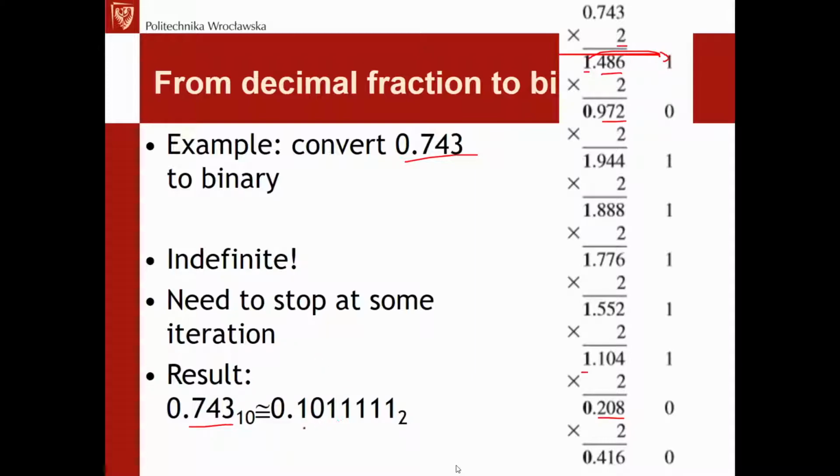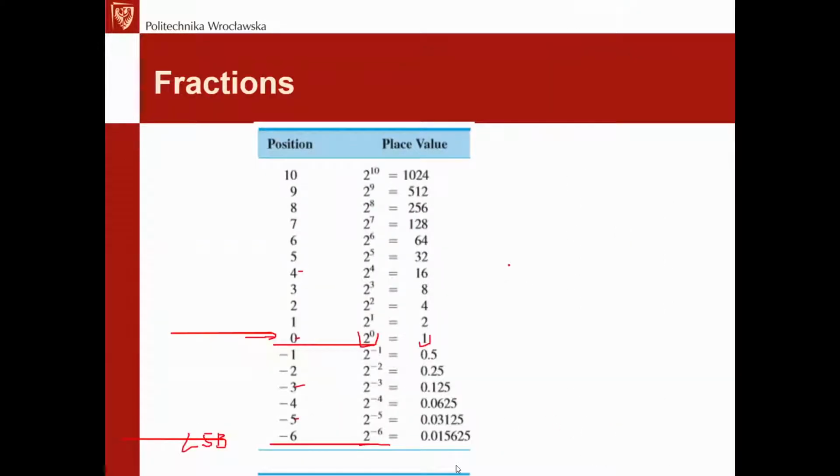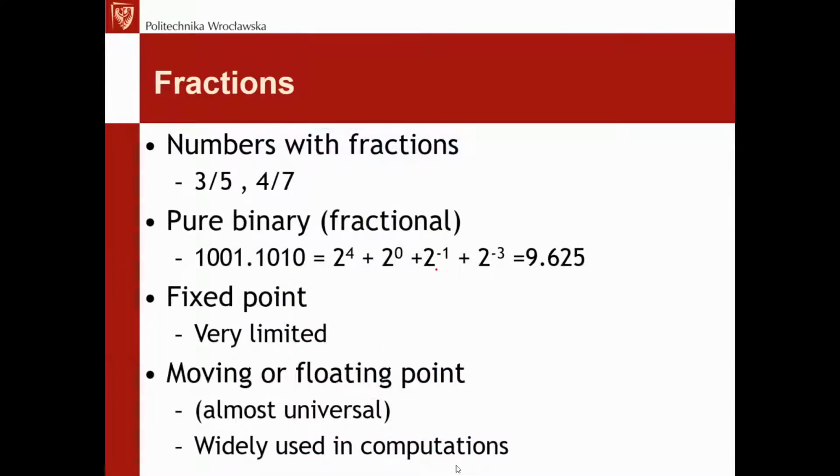Of course, we stop the iteration at the size of our number, the size that we want to use. Going back to practice, there is little sense of using fractionals when we are dealing with 8-bit arithmetics. So in 8-bit microcontrollers, the 8-bit fractionals allow us, like here, a precision of 1/16, which means that we have some fractional precision, not the greatest.